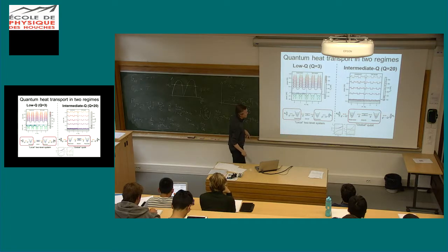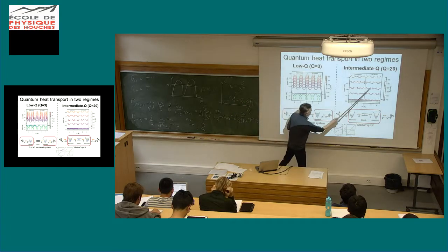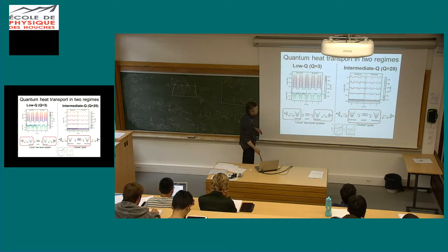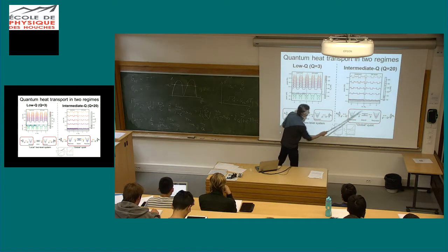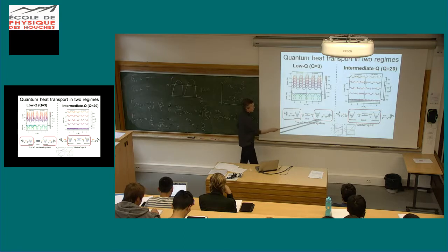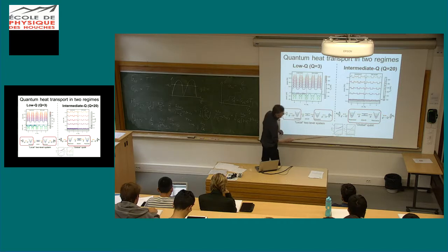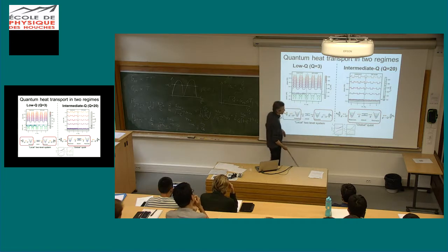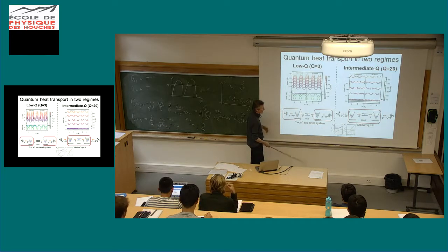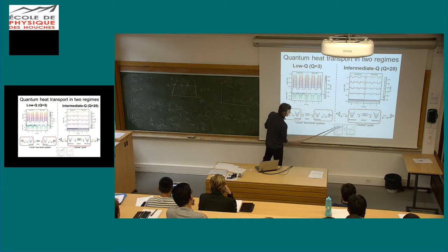And this is confirmed by several observations. Well, one observation is that the model that we wrote down seems to capture it very nicely. But we also could measure the level spectrum of this system when we didn't have these resistors connected, and this is a result from the spectroscopy measurement. So one can see that there are these lowest levels. There's an avoided crossing there, and this is what comes out when you just simply diagonalize this system here, assuming that the resonators are equal. If they're unequal, there's a little bit of splitting there as well.